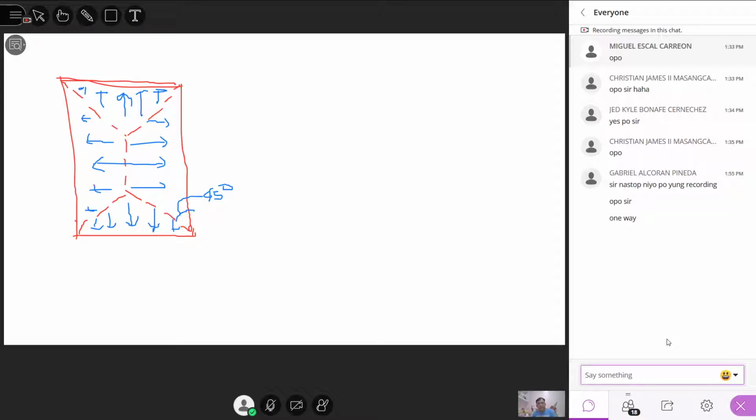So considering this slab, we now have 4 supports. You have a beam here, another beam here, and another beam here. So the tendency is that the loads of the slab will be transferred in 2 directions and should be shouldered by the 4 beam elements. You have loads going in this direction, in that direction, and loads going to the right and to the left. So if you look at the reaction of the slab, it is a two-way reaction.